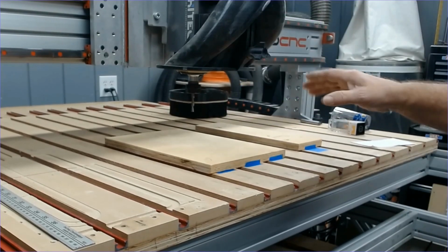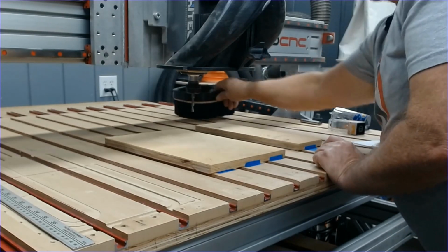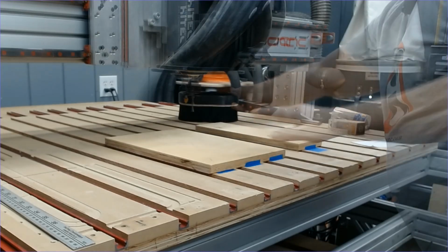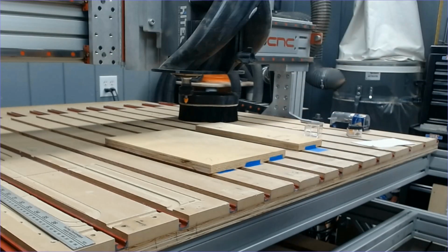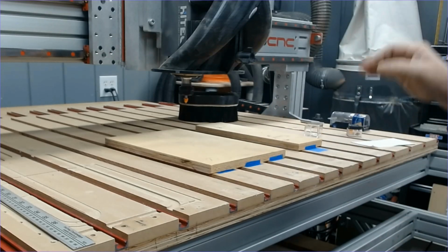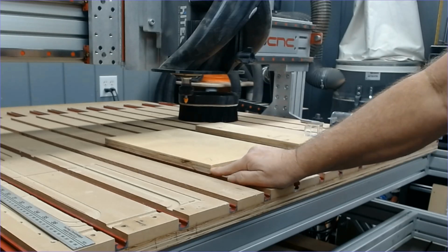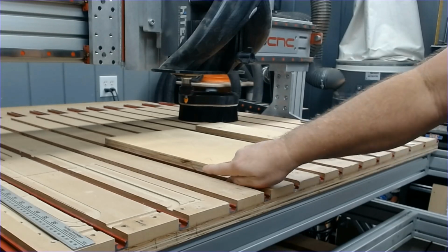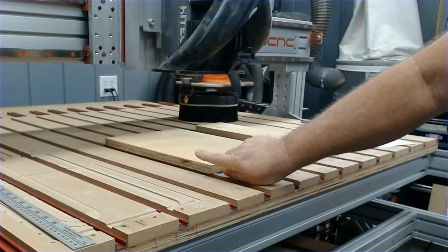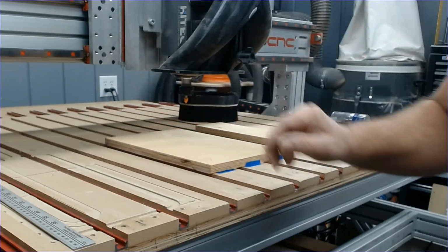I'm now ready to turn on the spindle power, put on my dust boot, and I can run my G-code. Now I have purposely reset X, Y, and Z0 to some sort of nonsense so I can demonstrate this method as well. Let's say you have your XY datum position or your origin set to the bottom left corner. This works the same way if you've got bottom right, top left.